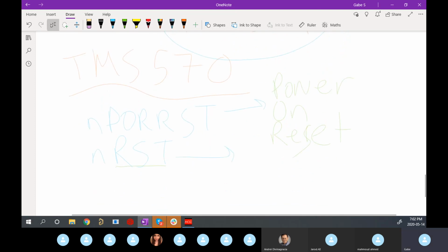And the difference between them, this one actually power cycles the whole chip. It's going to reset power for the whole chip and start everything again. So the code will begin again, but you'll have a full power cycle of all the peripherals inside your microcontroller. So anything drawing power, GPIOs, clocks, peripherals, communication protocols, all those powers are going to be reset. And usually you have a lot of different rails internally.